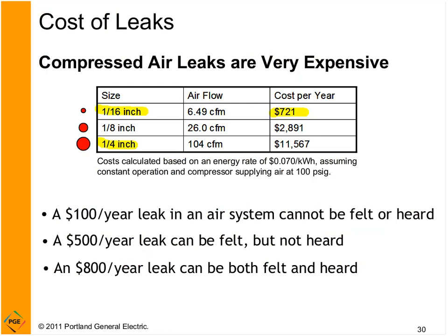Quarter-inch leak. Look at that. $12,000. Then we have a category of leaks where I probably can't hear or feel a $100 leak. And then as the leak becomes worse, where I can both feel and hear it, walking by and I can feel the air on my skin, $800. I guarantee that you have some of these leaks in the plant. Okay, not to badmouth or talk down. That's not at all the point. The point is that they're just out there. I mean, if I had a plant, I'd have them. You can't get away from them, but you've got to keep on top of them and fix them.